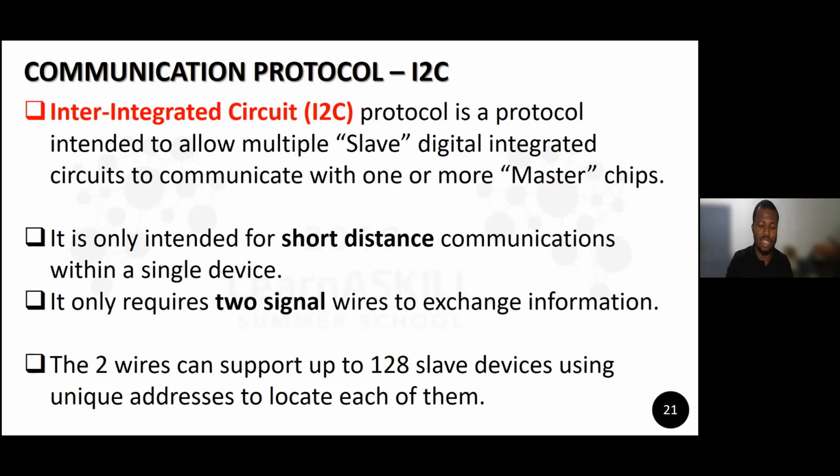All right. So the I2C, like I said, uses an address system, and that makes it possible to connect 128 slave devices to the Arduino so that the Arduino can communicate with them. Now, if you've used something like an RTC module before to provide clock and time for your Arduino, you realize that you are always connecting it to the SDA, and you use an address. Typical I2C devices usually use the 0x68 address, but some of them are configurable. You can always change them.